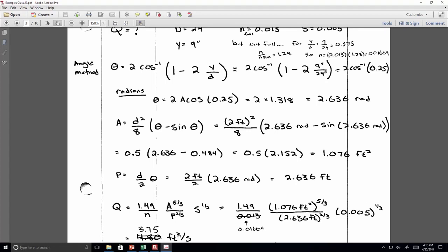If you don't know the depth of flow, then you can't find the flow rate. So they would always measure, they would never arbitrarily guess. I may not follow you. So they may make some assumptions when they're sizing the pipe, but you can't say how much water is going through the pipe without knowing something about the water depth that's there.